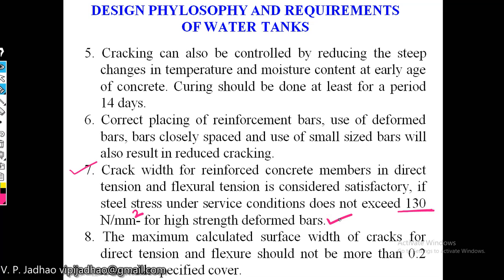The maximum surface width of crack in tension and flexure should not be more than 0.2 mm with specified cover.